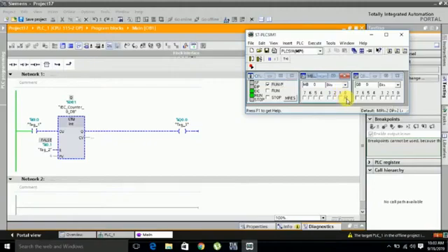I will show here. First I will use one bit and give it on, I0.1. One time I turn it on and close. Here is one time on. Then I will go second, third, and on the fourth it will be on. You see here, when the counter value is 4, it matches our PV, so it will give the output. When we reset, the value is again 0.